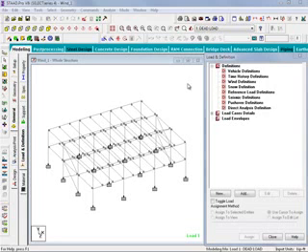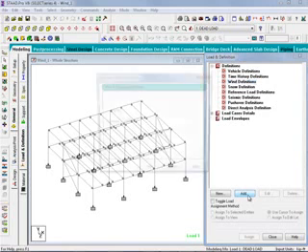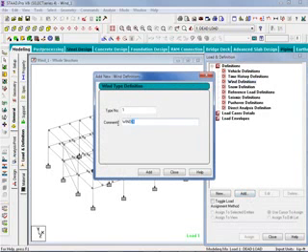We are now ready to create our first wind load definition. I'm going to go over to the Load and Definition dialog and highlight the wind definition item, and then I'll click Add. Here I just simply need to name my wind load, and I'm going to call this Windward X for the X direction, and I'm going to leave the type number set to 1. This type number will later let me identify this wind load definition when I incorporate it into a load case detail.